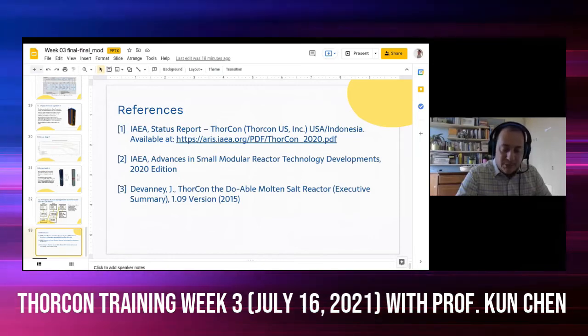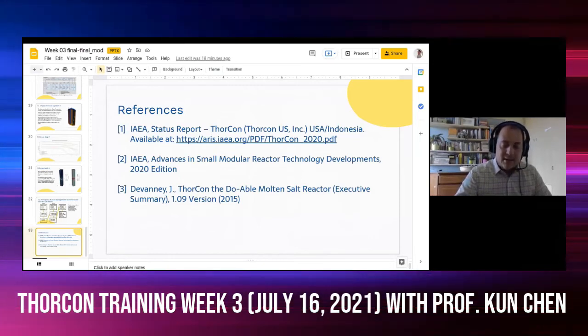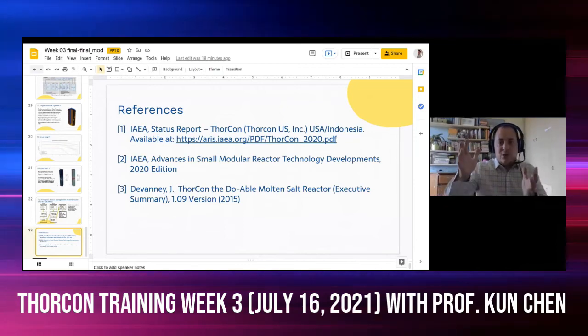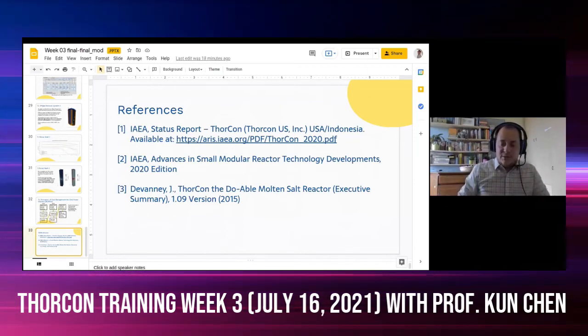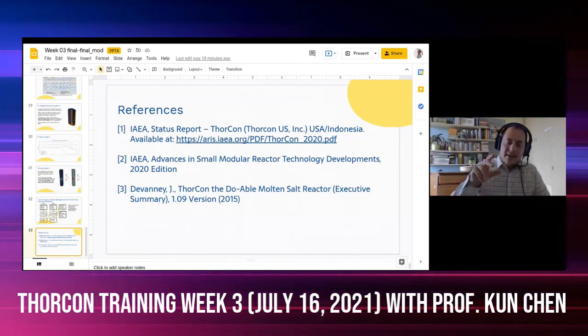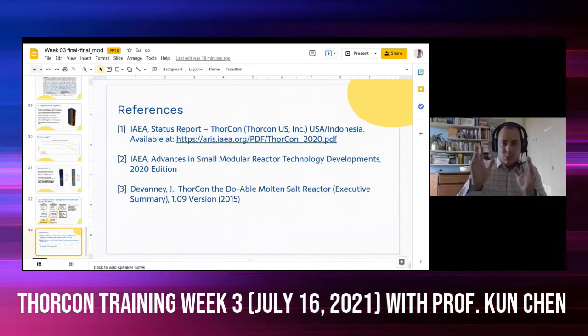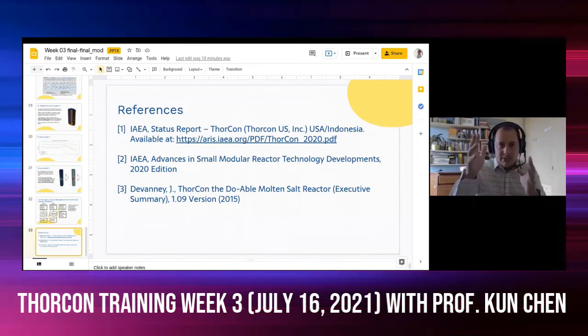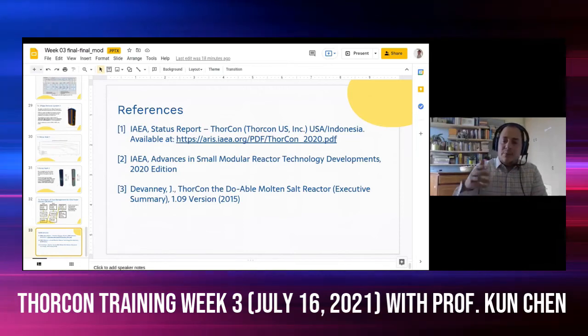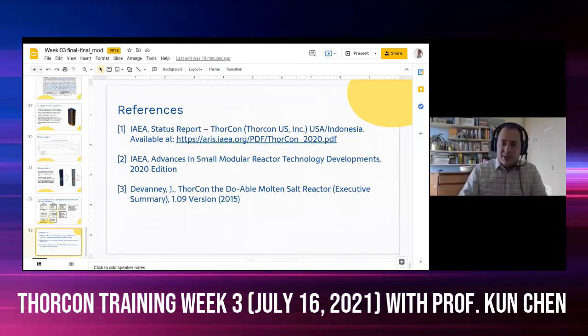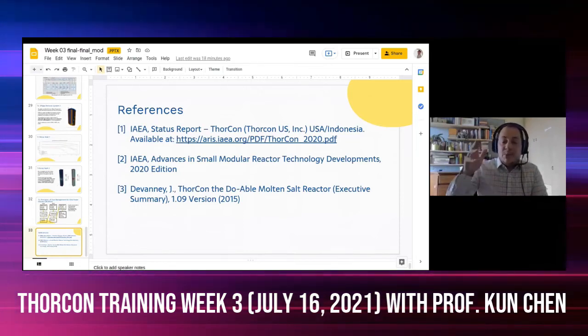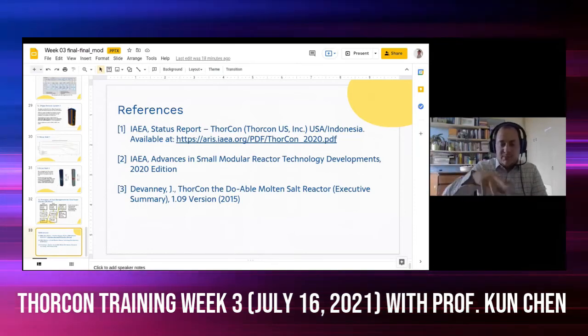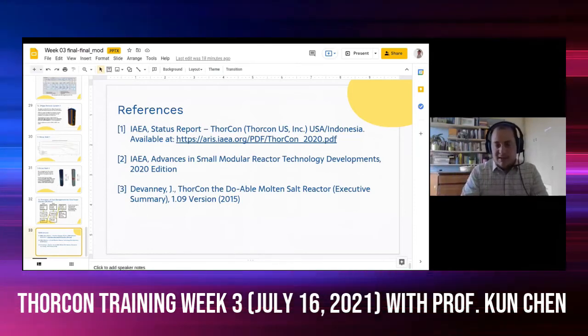Serpent can be coupled directly in the sense that given a reactor geometry, it is straightforward to take the density and temperature distribution of a material, let's say salt, inside the core from the solution of a thermohydraulics code and input towards that code the power distribution, which is exactly what we do.